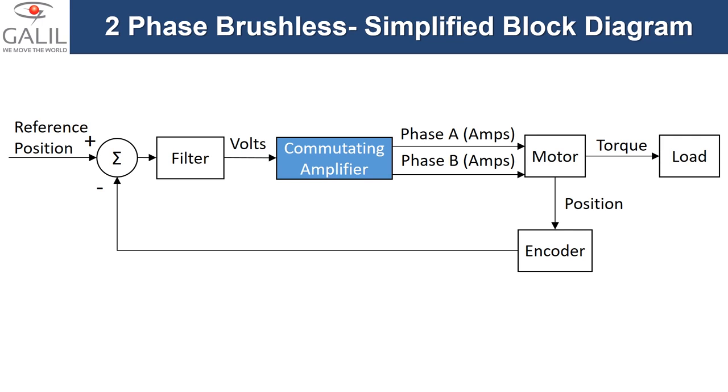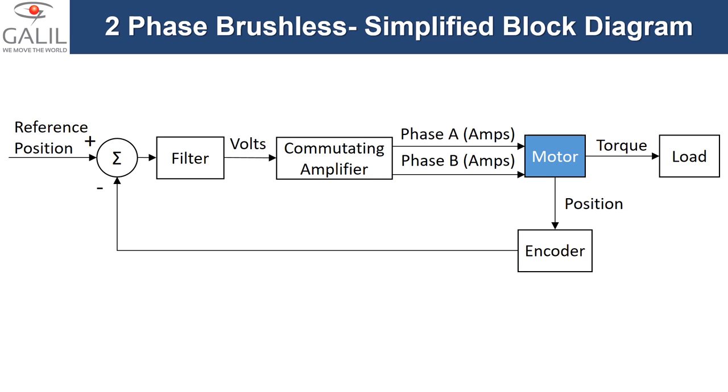The controller doesn't command steps, but instead commands a voltage signal that is directly proportional to the desired torque. The amplifier then produces only the current that is necessary to achieve this torque. This current moves the motor, and then while the motor moves, the encoder moves. The position data then gets sent back to the controller. While this is like a brushless servo, the motor mechanics are different and require a different form of commutation.